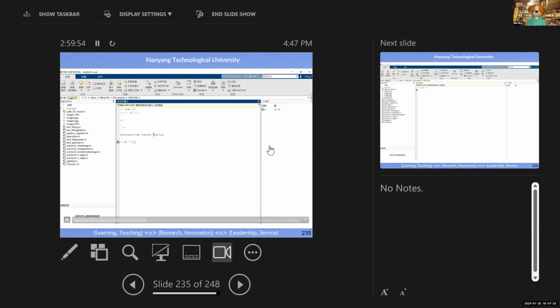So you use MATLAB, just key in, then you call the root locus command, enter. I do not know whether in China they give you free access or not. For NTU students, they have a free license to use MATLAB, so it's not an issue. This just demonstrates to you how to use MATLAB to key in a transfer function G(s). This is the transfer function.